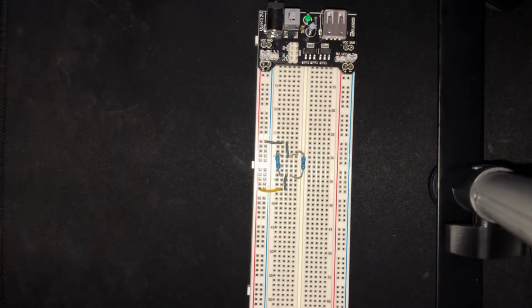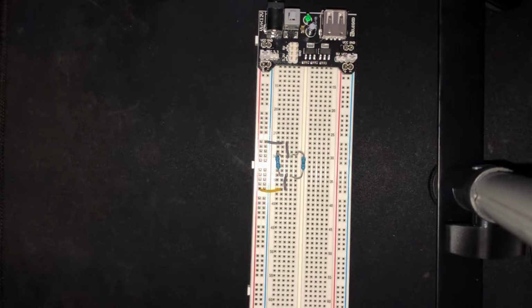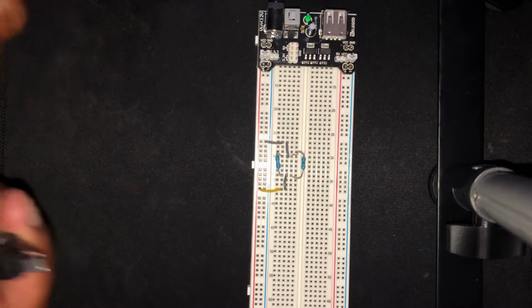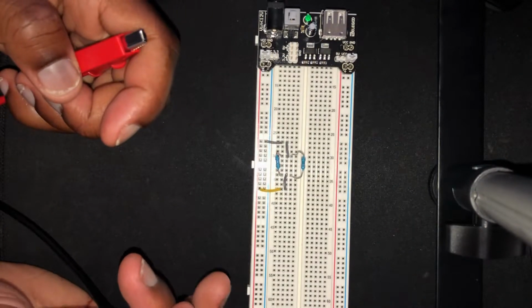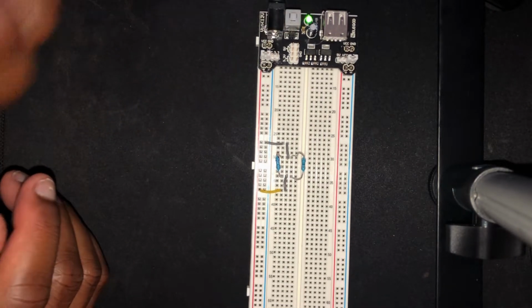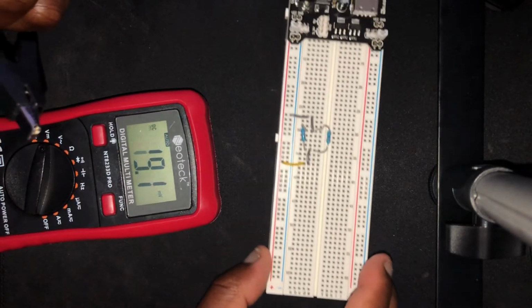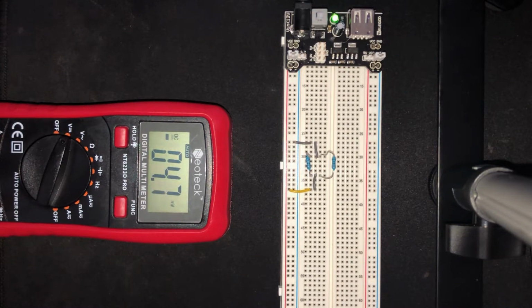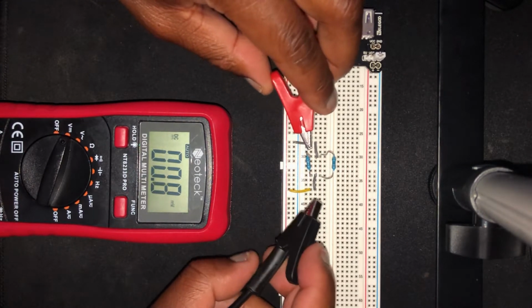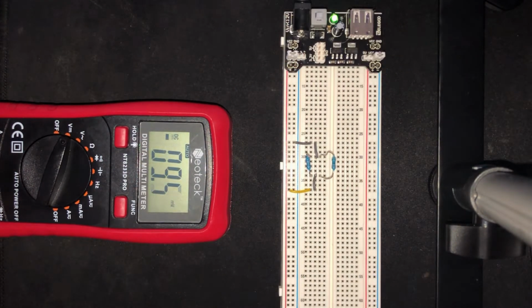Voltage is a ratio. It's the amount of energy divided by the amount of charge. So if you lower the amount of charge passing, you lower the energy, but it's in proportion. So you're going to get 5 volts either way. So let's switch this circuit on and let's measure. So set this to measure DC voltage. So this is the 220 ohm resistor, I think. Doesn't really matter. We should see about 5 volts on both of them.